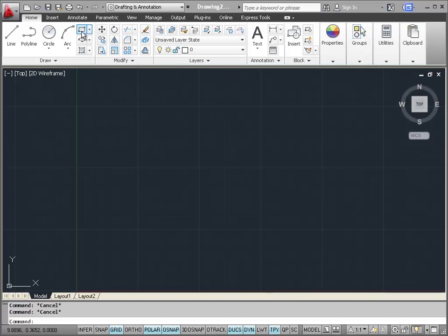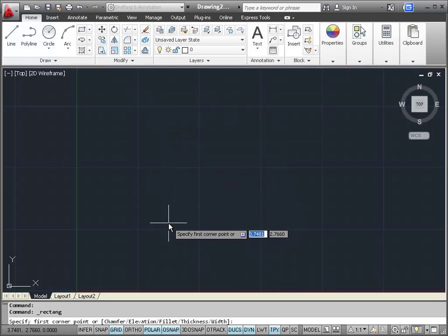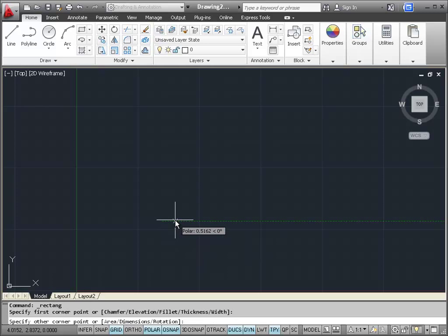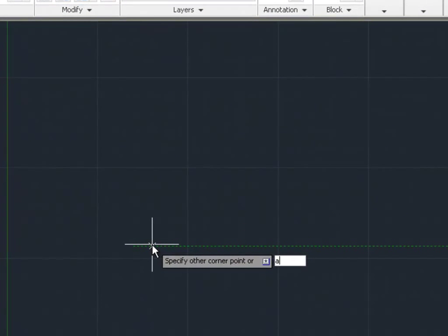You can also draw a rectangle with a specific area and let AutoCAD assist with the calculations. So for example, we've clicked the rectangle command and we start with the first corner of the rectangle, but then we enter A for area, and let's say we want the area of this rectangle to be 70 units. So we'll enter 70. Then AutoCAD will ask us for a length or a width. And whatever we give it, say we give it the length, AutoCAD will then calculate what width we need to have a rectangle that's exactly 70 square units.